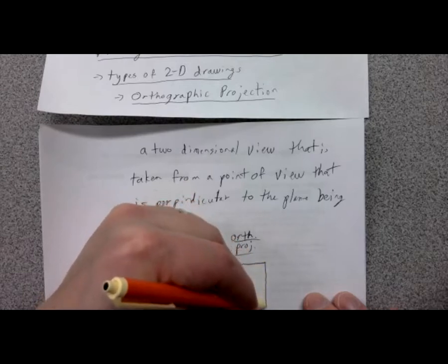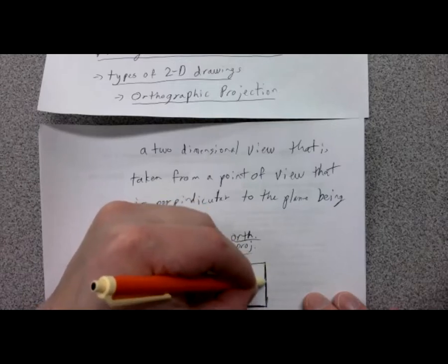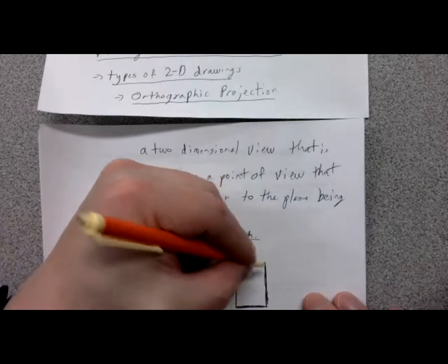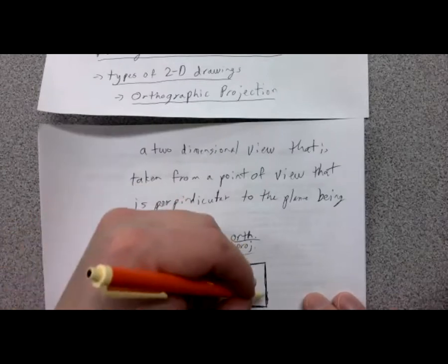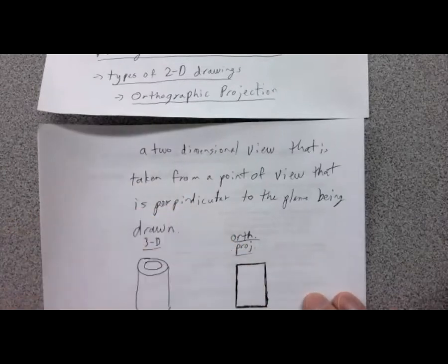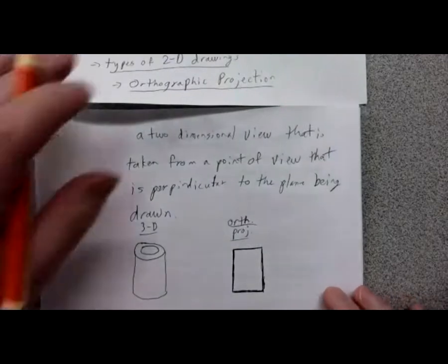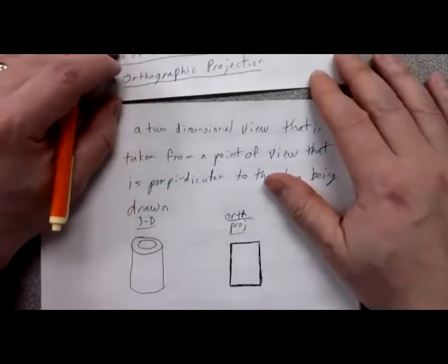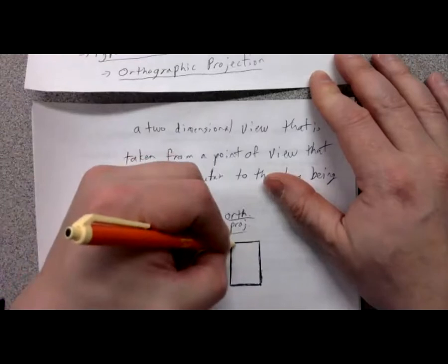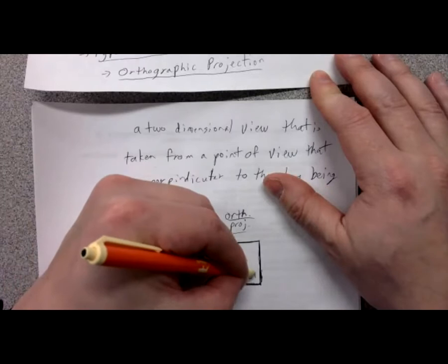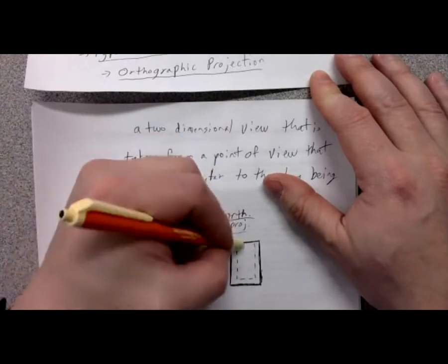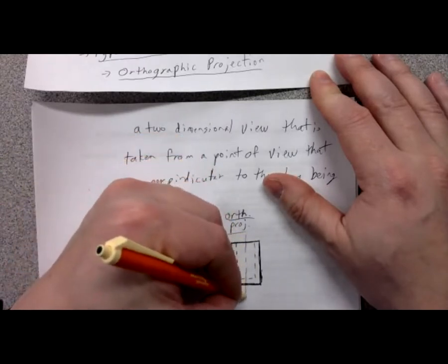And so if I'm looking right straight at it, I'm not going to see curvature. I'm going to make these thick, visible lines here, so I'm going to go over them a couple times. If you've got different thicknesses of lead, you can make your lines thicker that way. There's a variety of ways you can make thicker lines, but you want to make sure those visible lines are in fact thicker than the hidden lines. And then we can communicate to the viewer, hey, there's something going on in here you can't see from this view. And if you like, you can communicate there's some symmetry right down that axis.